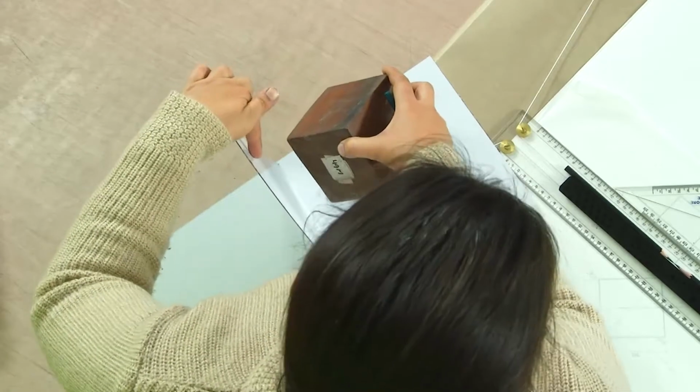So, in the front elevation, we will be seeing the axis inclined at 30 degrees or whatever angle to HP. And the rest of the things will remain as they were if it was kept like this, perpendicular to HP. Now, when we tilt it like this and then we further tilt it, it's the same phenomenon happening as we learnt in doubly inclined lines.